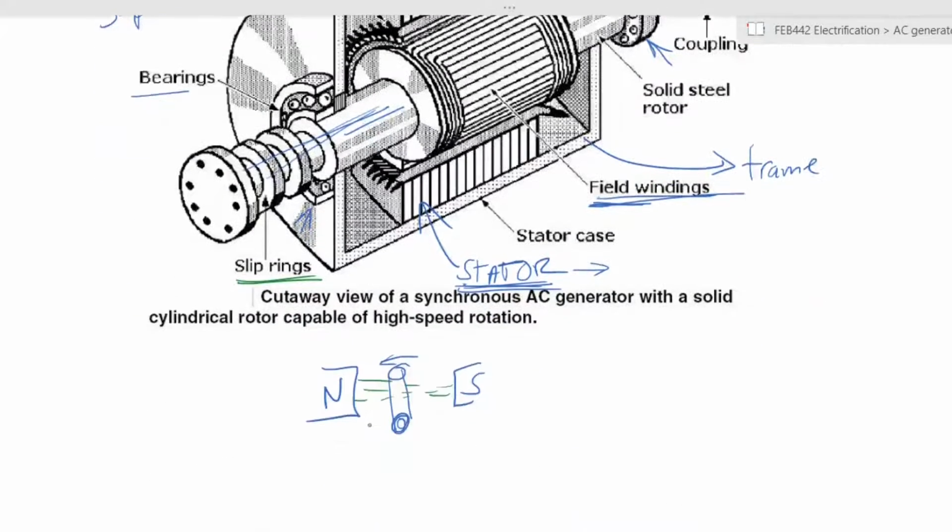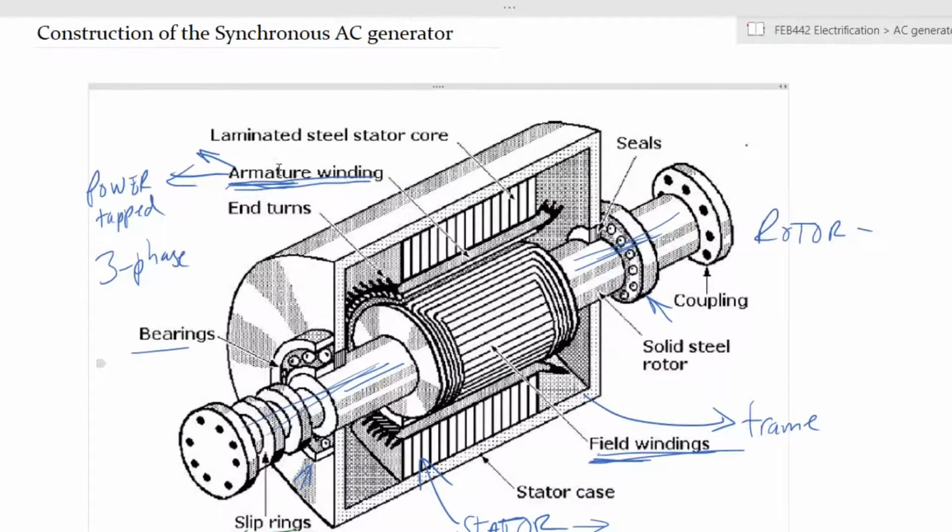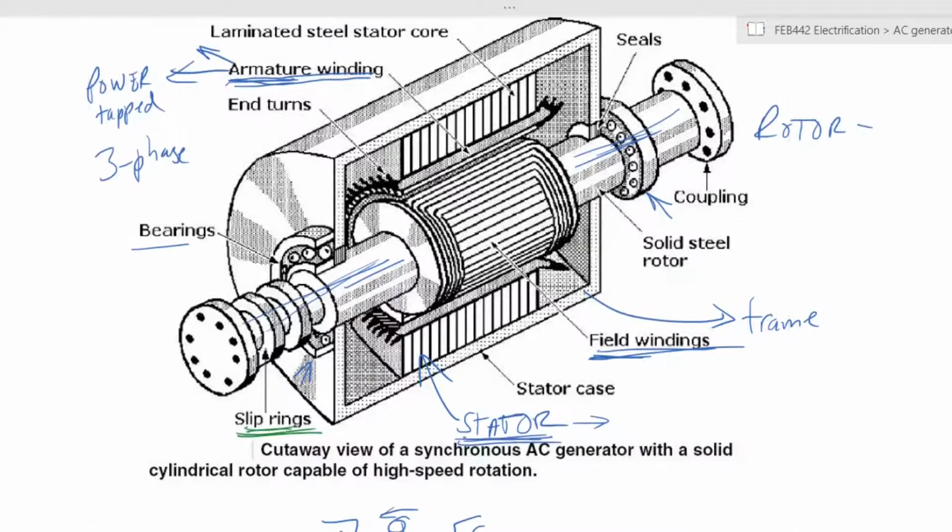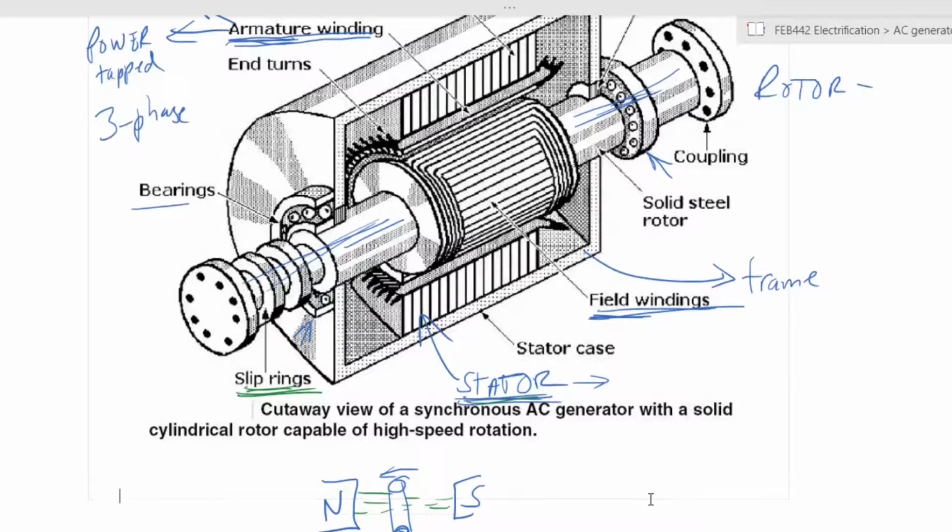If the armature was rotating, you would need to have slip rings that would take off the power. So instead, practically the engineering convention is that the part of the generator having heavier current, the current carrying conductors, which are the whole purpose of the generator, are the ones that are stationary. So you have your armature mounted on the stator in the case of your AC generator.